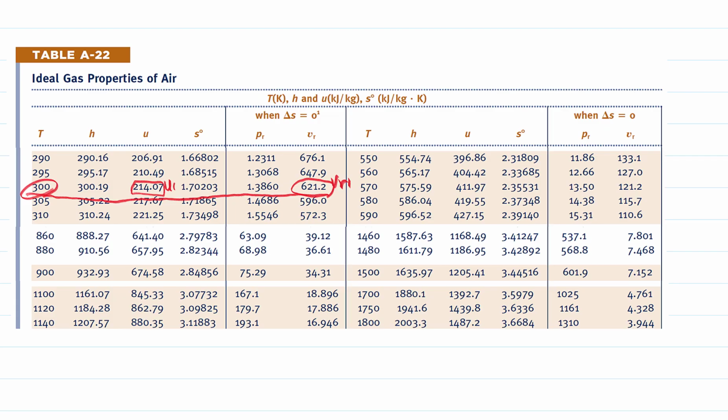So see the tables and find where the relative specific volume 34.51 falls. It is between these two numbers. So do the interpolations with vr2 to determine the corresponding temperature and enthalpy, T2 and h2.